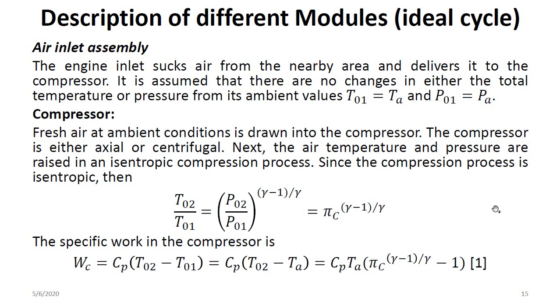And the specific work consumed in the compressor is equal to the specific heat multiplied by the temperature rise between entry and exit of the compressor. So if you multiply the temperature rise by the specific heat, then you get the specific work done to drive the compressor.